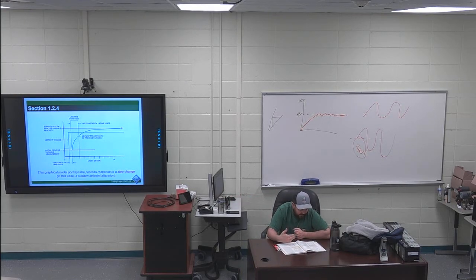In the time constant bullet point, the sentence that splits the columns is highlighted. A full response from the end of the dead time to arrival at steady state requires 5 time constants to pass, 7.5 units in the graph.